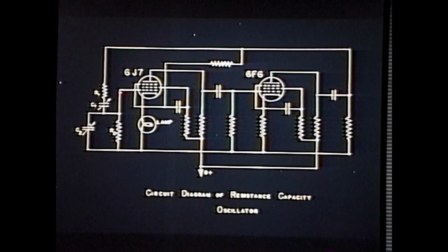So this right here amounts to the positive input to the op amp, if you will. And the gain stabilizing feedback, there's a resistor coming down here, tying into the lamp. So there's the bridge right there. There's the top of the bridge. There's the Wien side, the negative input, the positive input to the op amp. Here's the other side of the bridge, composed of this resistor and the lamp going down here to the cathode, which is the negative side of the bridge.